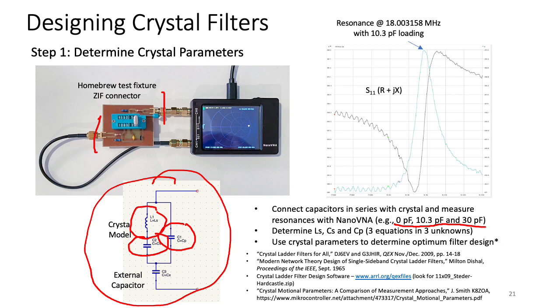that we see. To do that, we're going to measure S11, but instead of displaying S11 as a vector on a Smith chart, we're going to look at the real and imaginary components of it and look at where that imaginary component goes through the origin. Alternatively, we could look at the peak value here. We'll see the resonance occurring at the position where the imaginary part goes through 0. There'll be a peaking effect in the other component.